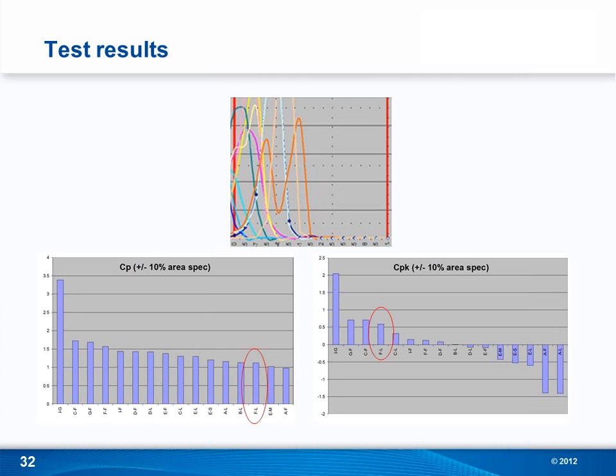And the reasoning would be larger apertures you can cut faster, so your aperture wall may not be quite as smooth as possible, but because they are large apertures, they have a high area ratio, so paste release is relatively easy. For the smallest apertures, you want to make sure that you have the best aperture wall possible, so you run it at a different cutting speed.